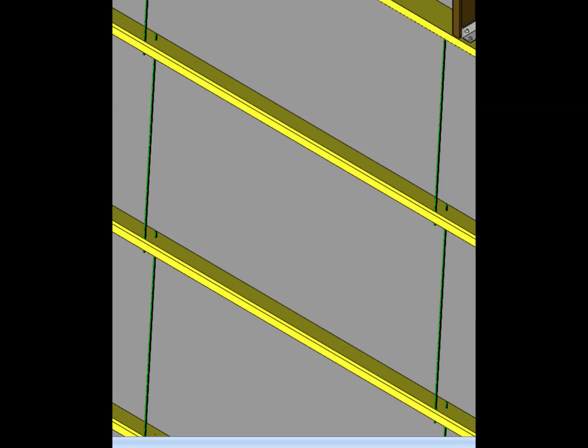The important point to remember is that the sag rod should always be studied together with the framing members to which it is connected. If we look at the sag rod alone, it may appear to be just a thin rod. But when we look at the complete framing system, we can understand why its location and connection are important.